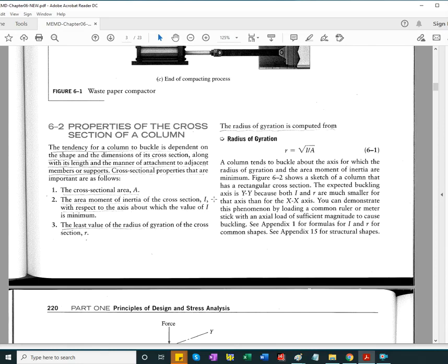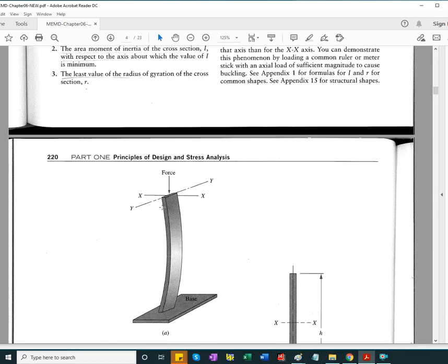It is elastic buckling or Euler buckling, and buckling depends on cross-sectional area, depends on the moment of inertia. Moment of inertia about an axis transverse or perpendicular to the buckling plane. So here, the moment of inertia about the y-axis proved to be less than about the x-plane, given the end conditions, the way the beam or the column is allowed to rotate or not.